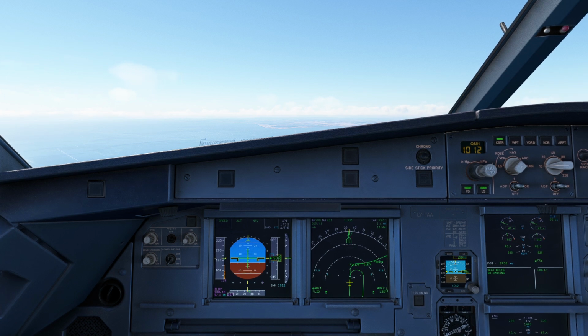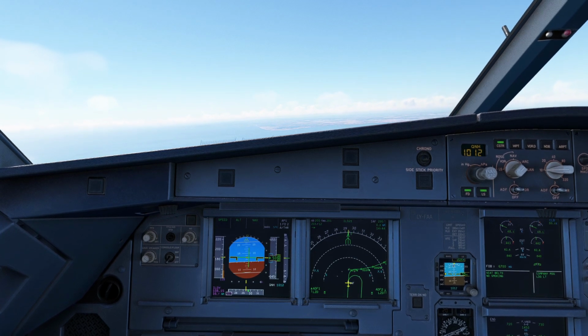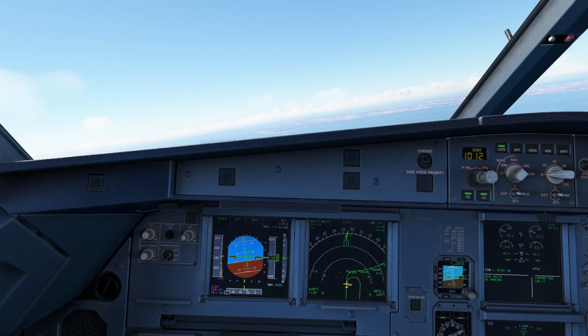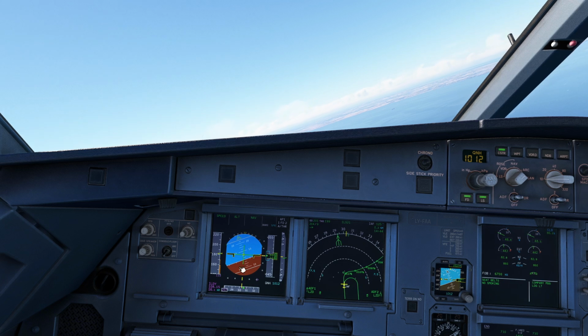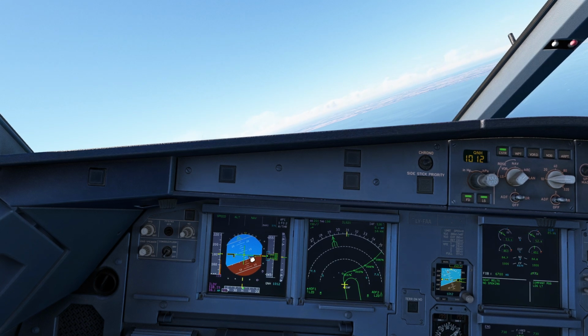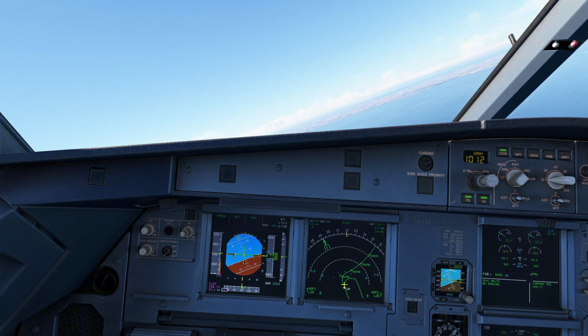But there is a big question. Is the flight director recommended during the visual segment? For a short answer, it's definitely not. It is generally not recommended to use the flight director during the visual alignment segment after an offset ILS. But why? The flight director will continue to command the aircraft along the offset localizer, even when you need to visually maneuver to align with the runway.